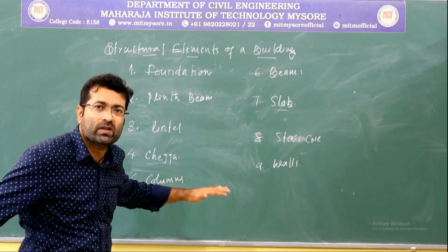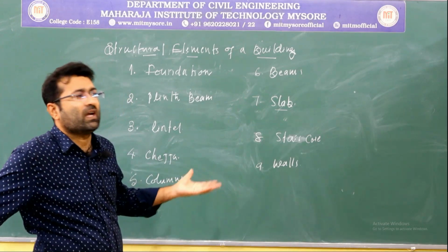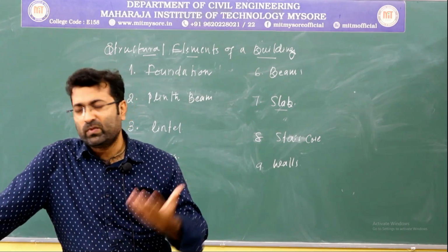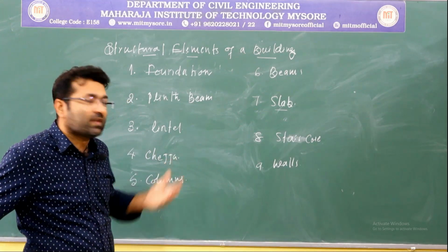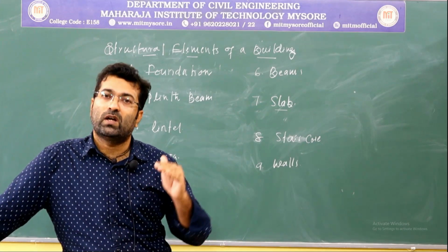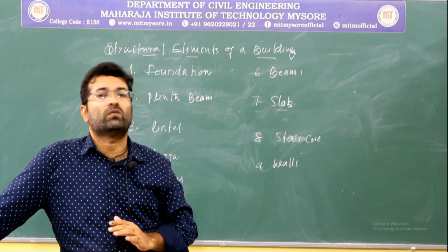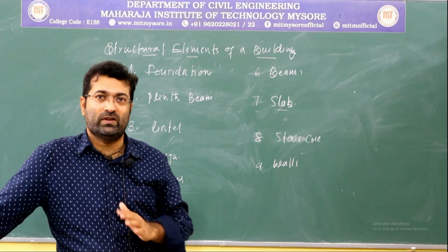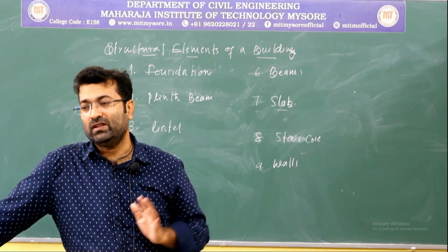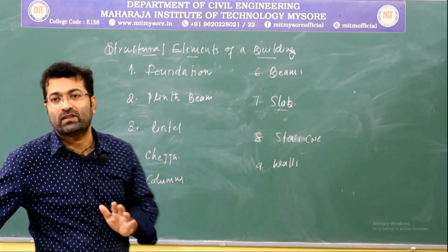So walls may be of brick construction, or stone construction, or nowadays we have new elements, like cement blocks or AAC blocks, many other hollow blocks and all other things. So we can construct with anything, but basically if walls are transferring the loads from the superstructure or loads from the slab to the foundation, then the walls are treated as structural elements. If not, then the walls will be a non-structural element in the buildings. Okay. So, these are some of the basic elements in the building.